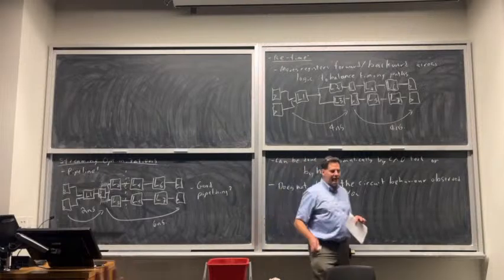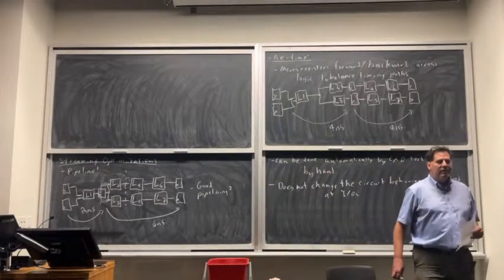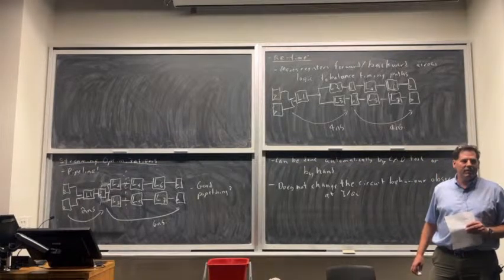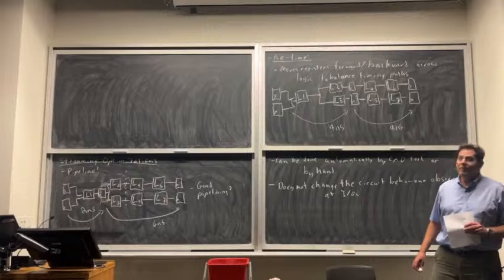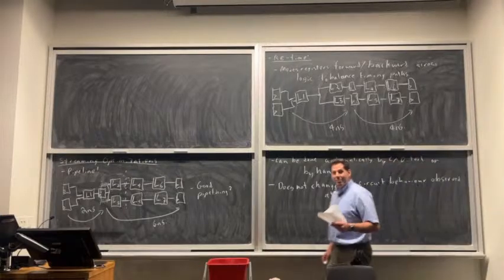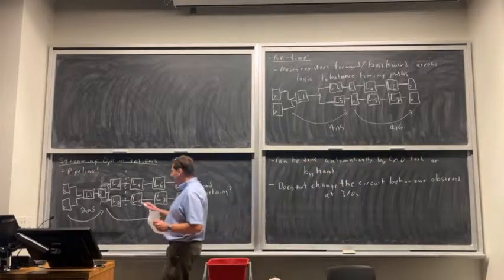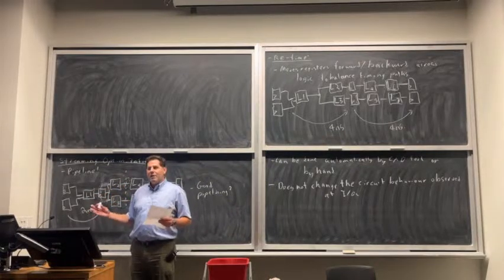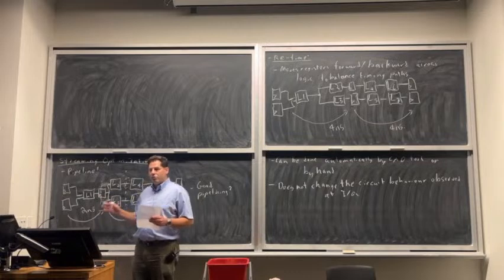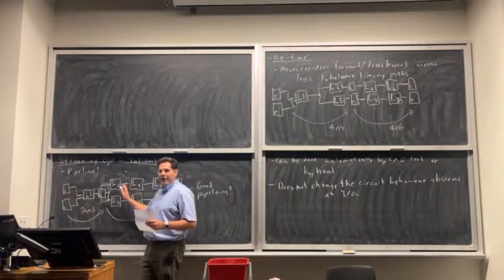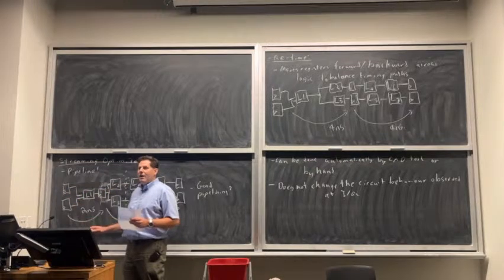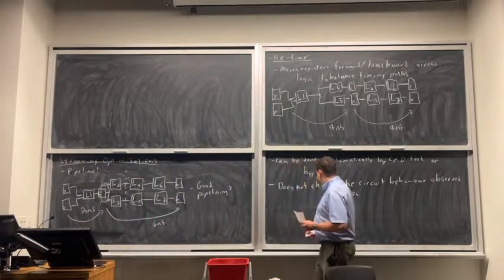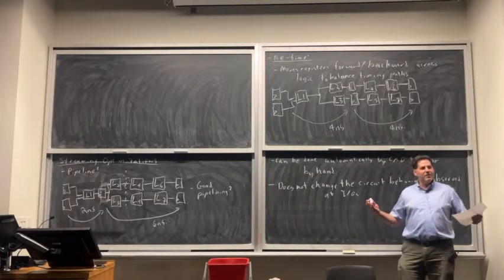What do you think? Maybe it's possible for retiming to take far more resources if it keeps pushing registers down, like a lot of fan-outs. That's actually a good idea. I didn't think of that, but you're right. That could happen. It is a resource trade-off. Retiming usually doesn't increase register usage too much because it pushes some things down, but it can push some things backwards. But you're right, in certain structures it could. That's a good point. Any other ideas?